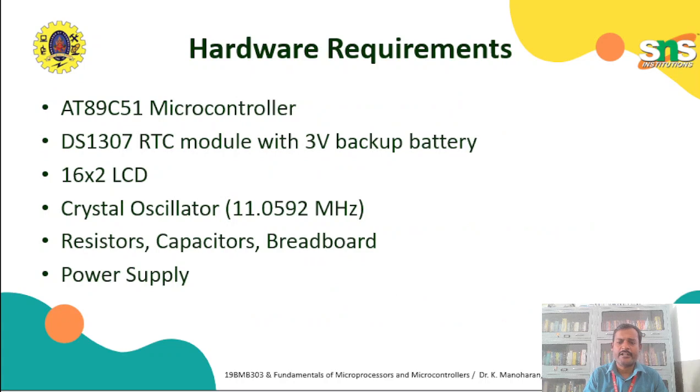Look at the hardware requirements. First, we need the 89C51 microcontroller. Again we need the DS1307 RTC with a 3 volt battery backup. We need the 16x2 LCD display for displaying that information. We need a crystal oscillator, and resistors, capacitors and breadboards for connecting. And we need the power supplies. We can use a general purpose PCB, or a specific custom PCB also.